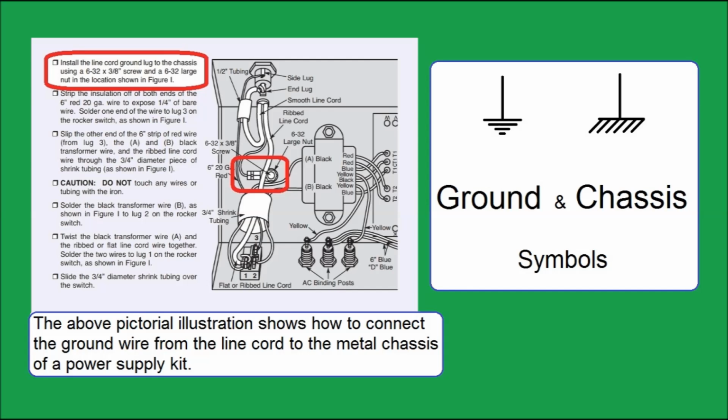Then other components higher up in the chassis don't require a line crossing the entire diagram to be connected to the chassis. They can be given their own chassis symbol to establish the connection. And this shortcut also applies to the actual physical circuit. For example, in a car, the rear lights only need to have their negative leads connected to the chassis of the car, saving a great deal of wiring.